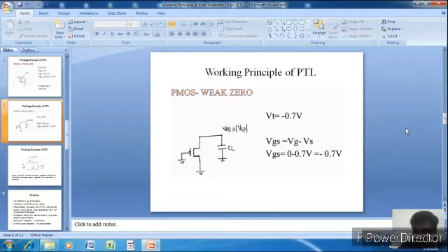And that is the reason why we also call the pMOS transistor a pull-up network, because it can transmit 1 safely. If VDD is the input, the output is VDD. And in the case of an NMOS transistor, we call it a pull-down device, because it can suitably transmit 0. That is, if 0 is the input, 0 is the output.